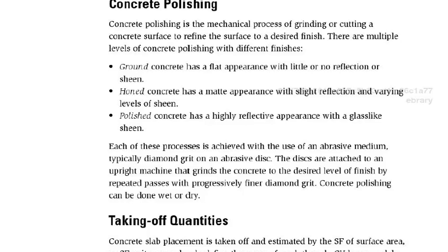And just to round things out for you, you should look to see if you need any polishing done on the concrete, but there are different finishes you can put on general flat work. A broom finish of some sort, or a burlap-dragged finish will work, but you also can grind concrete to make it flat, especially if you need tolerances for setting equipment. You grind it. You may hone the concrete, and this starts giving it a light polishing, but also makes it more flat and accurate.